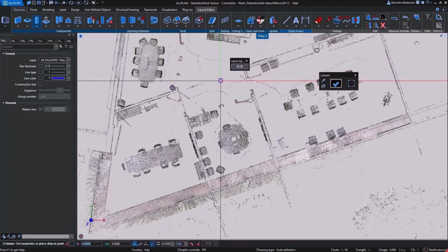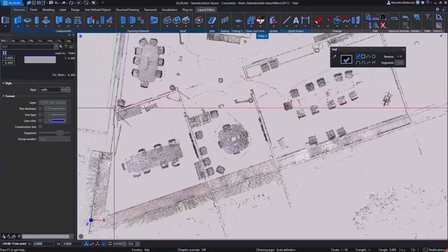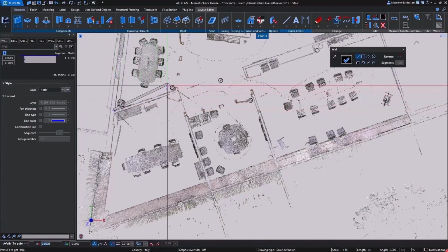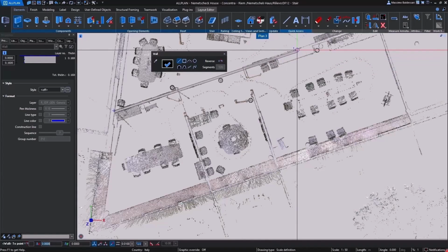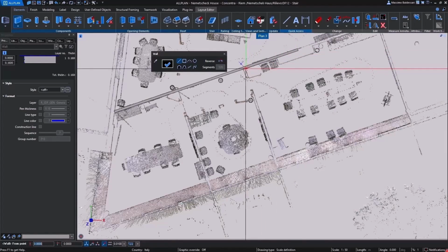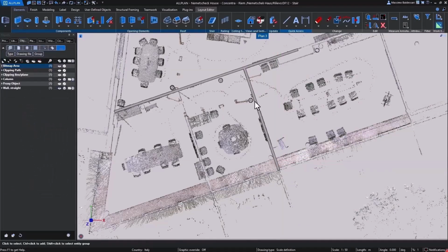Following that process, I could use the standard and familiar Allplan commands, such as columns or walls, to carefully reconstruct the portion of the model I'm interested in. In this specific case, I'll need to completely flip the orientation of my wall. So I'll go ahead and place my wall directly up to this point, then create another section in this other area over here. And I'll either recreate or directly copy the wall I just generated.